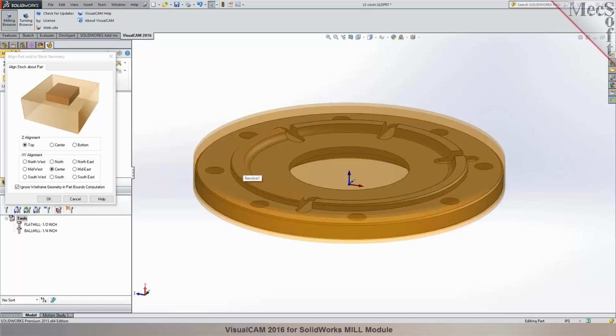Am I correct? Well, that won't leave any allowance for just that face to the machine. Can you put it in setup? Yeah, for the Z, I can specify. This is basically aligning the stock to the part. So we would then establish the origin. So since your part is 0.875 thick and the part is 1 inch, so do you want to leave material at the bottom, or do you want to remove the material off the top when you're doing a facing operation? So to bring it down to the actual thickness of the part.